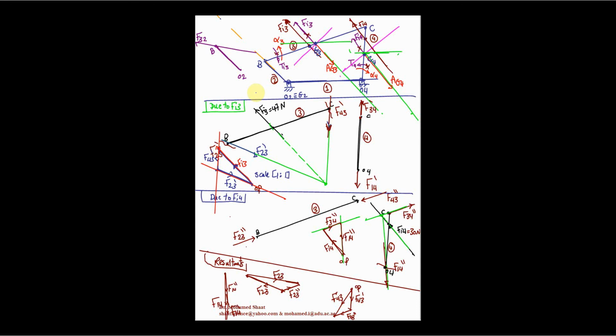So definitely the other force, which is F12 at point O2, should be opposite to this force but parallel. So it's gonna be parallel but opposite in this way at point O2. And this definitely is gonna give us the direction of the F12 force. Make sense? Then from either point O2 or point B, you're gonna draw a line that is normal to the two forces. This is gonna give us the distance D or the distance H.